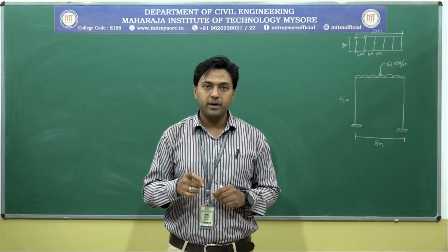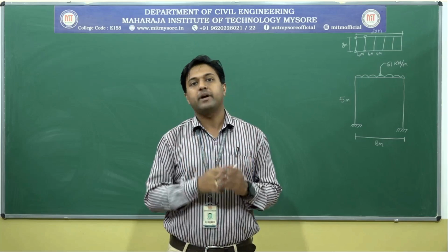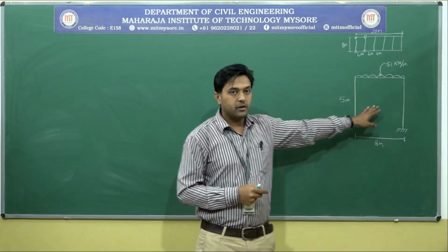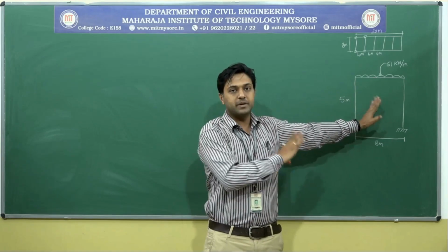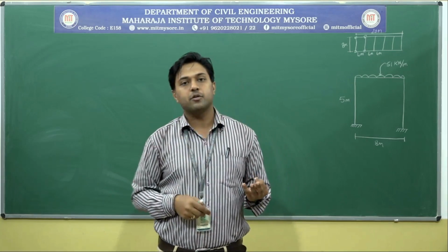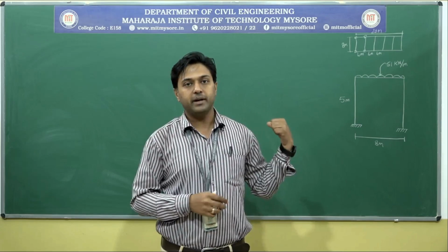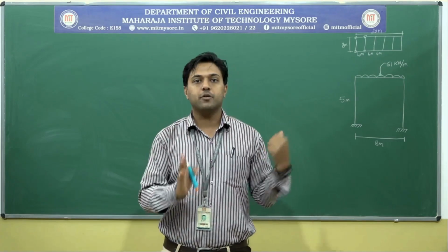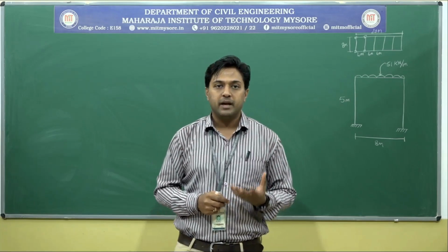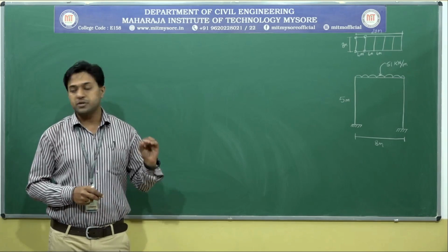If I want to know the bending moment, I want to know the loads. Loads I have calculated, I want the bending moment now. So there are many methods to calculate. I need to analyze this particular frame structure. It might be moment distribution method, Kani's rotation contribution method. Like that there are many. For this particular topic, I will be taking Kani's rotation contribution method to get the bending moment values. Okay. So now let me take up Kani's rotation contribution method.